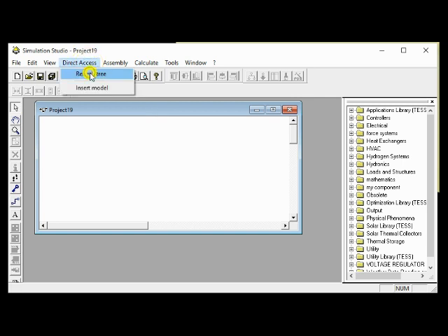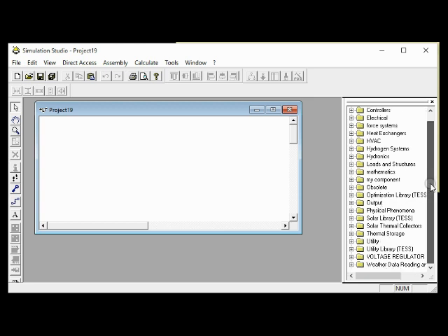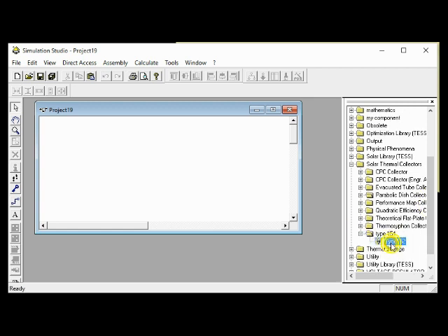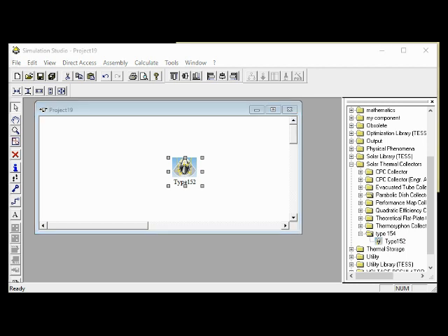So I'll close this and come to new, empty Trnsys project, create, and once this window pops up, you can see what's called direct access. You refresh tree, which refreshes this window on the right, and then you see that your new component will appear under solar thermal collectors, as you can see it here, type 152. So you can drag or click this and click into Trnsys. You can see the type has been created. So this is all about creating new types in Trnsys.